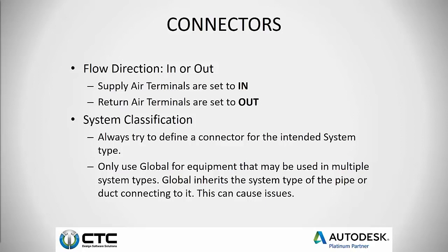Another important one is flow direction. Is it in or out? Now, supply air terminals blow air out, but the connector sees that information as being air supplied in to the family. Return air terminals, conversely, send it out or back into the ductwork.